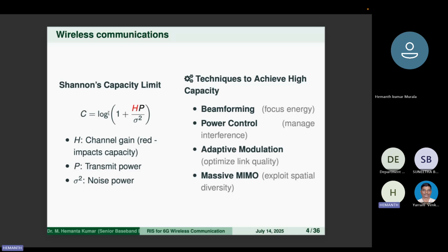We can extract H. So I can use some technique called the beamforming technique, that is zero forcing and MMSE technique. Okay. So what does the beamforming technique mean? H, I know. How do I know? I will tell you later. First I know the H. Clear? So while I am transmitting the X, this is the channel, and I know the H. Before transmitting this X, I can multiply it with some equation. That equation is H Hermitian H inverse H Hermitian. Got it?